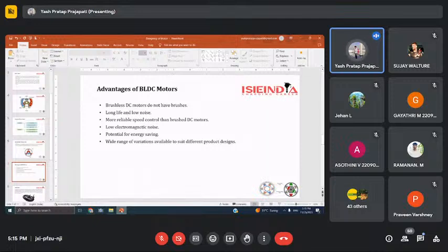With a stepper motor, holding the position of a structure such as a robot arm would require a relatively large and continuous current. With a BLDC motor, all that would be required is a current proportionate to the external force, allowing for more power efficient control. BLDC motors may also be replacing simple brushed DC motors in golf carts and mobility carts. In addition to their battery efficiency, BLDC motors can also deliver more precise control, which in turn can further extend battery life.